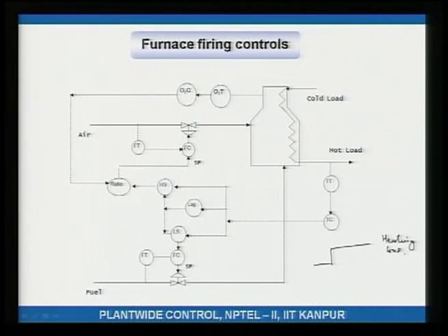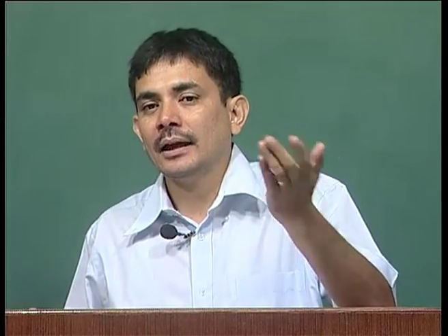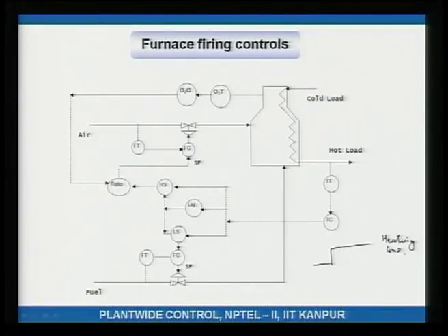However, in order to ensure that during the transient you always have more air than fuel, air should go up like a step and the fuel should lag behind.